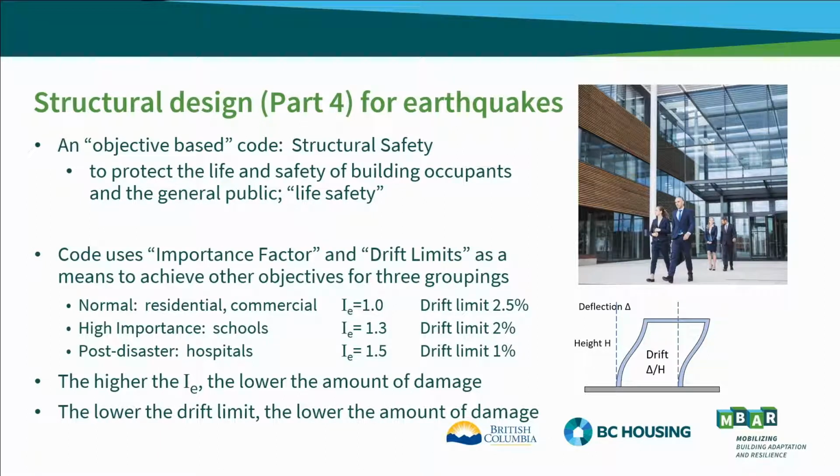So the higher the importance factor and the lower the drift limit will result in the lower damage after the design level earthquake.